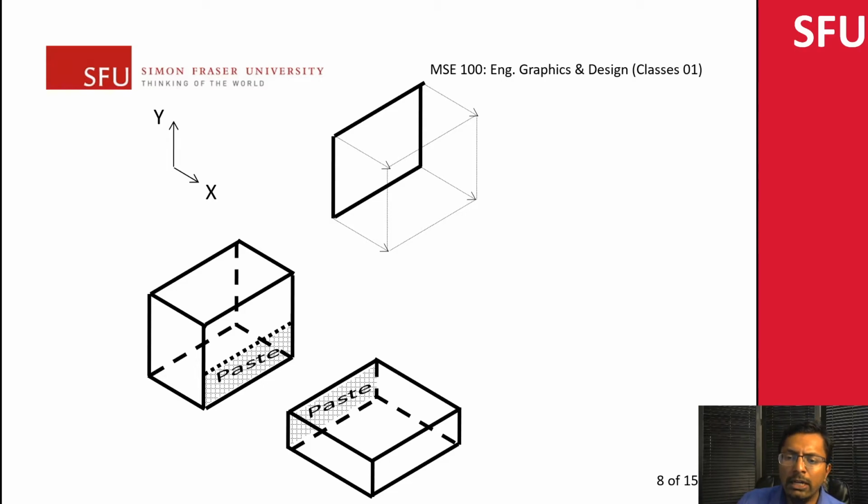In order to do that, I'll extrude the object first and then create a second sketch on the extruded face here. You're thinking about sticking it here and then extruding it further out. Maybe the laser pointer looks better. So you're basically going to stick this face here and then extrude it further. Let's see how that works.